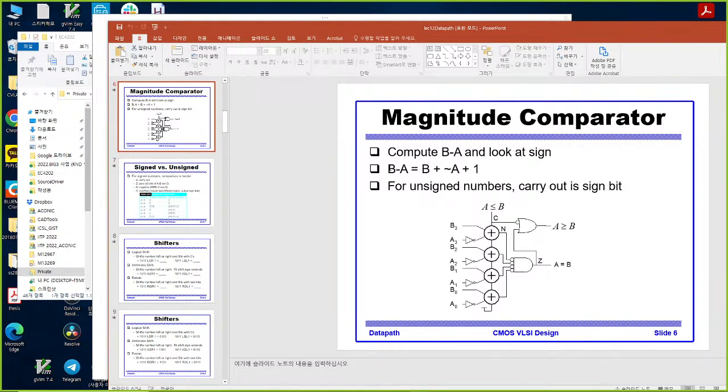Originally B was positive and A is negative, and then subtracted, but the output sign becomes different, negative then positive. In the other case, B started with a negative value and A is positive, then subtracted too much, so the result sign is positive, different from B, then it becomes overflow and underflow.